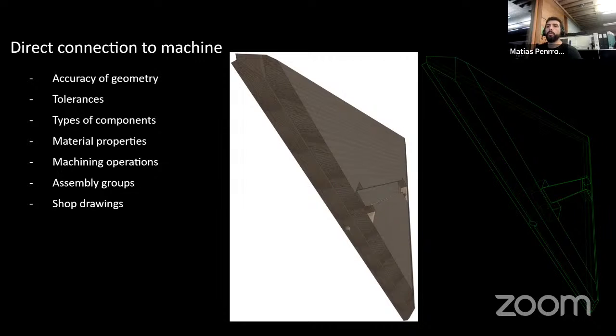So what are my assembly groups? How do I organize my construction site? Because prefabrication is one step, and if done properly, you can assemble this in just a couple of hours. Nowadays, you can assemble a whole house in one day if you want, if done properly. So organization and planning is really important. Also the shop drawing, so for the humans to assemble it.